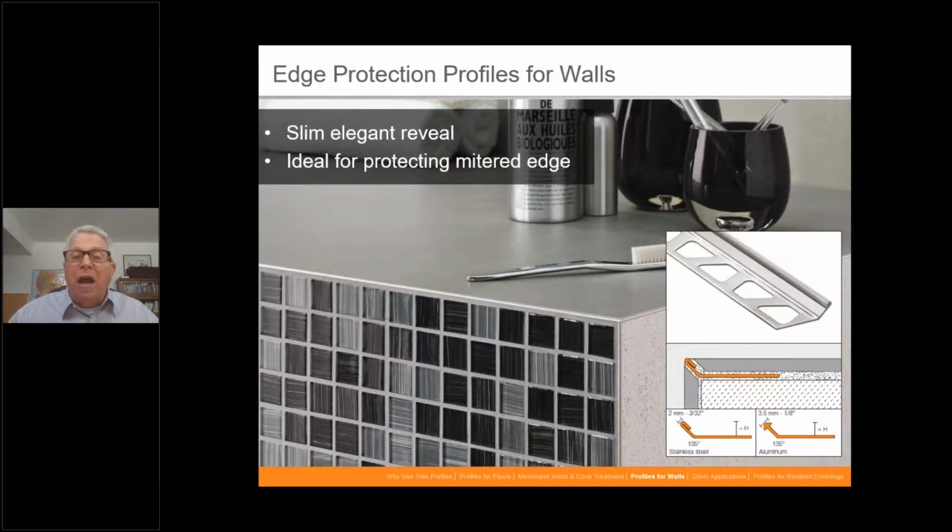Mitering tile has been around as an alternative, but it still leaves the tile quite vulnerable and doesn't really look good because the edges of the tile will, in many cases, chip when you run it through the miter, through the wet saw. So keep that in mind.